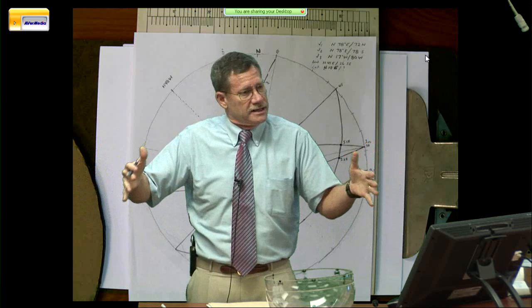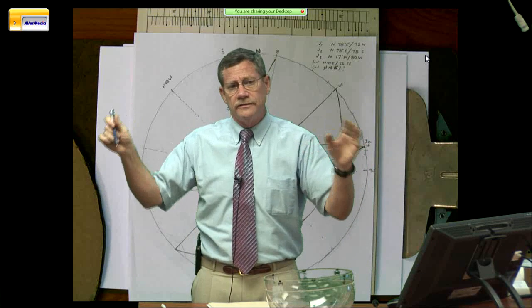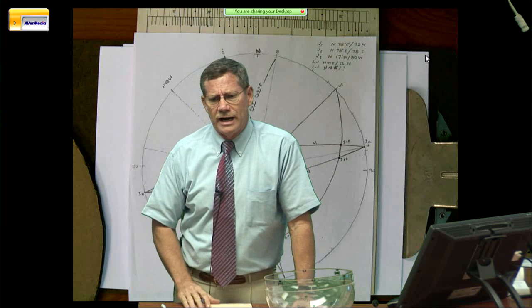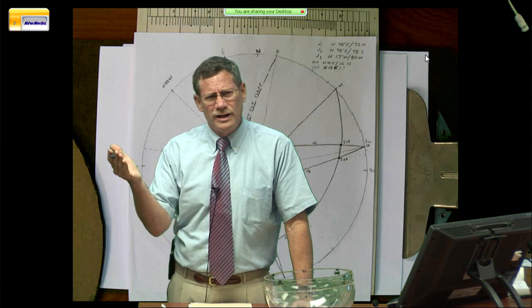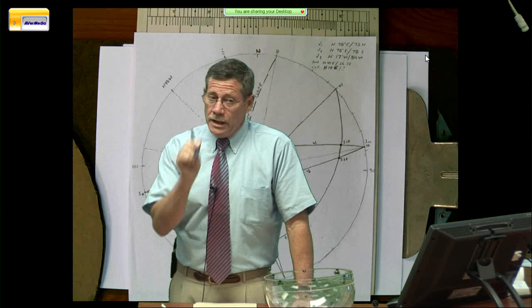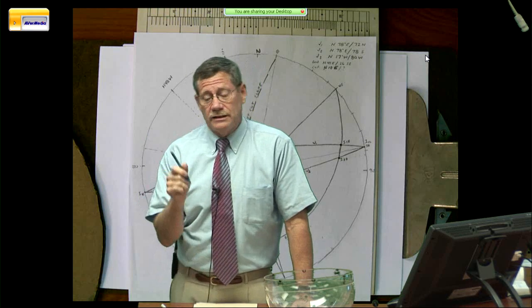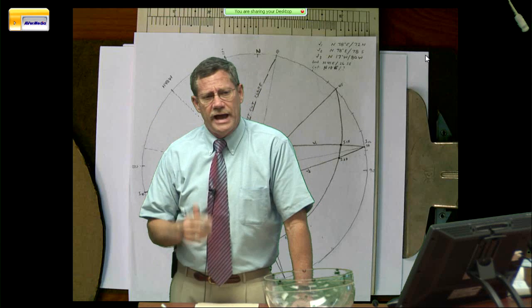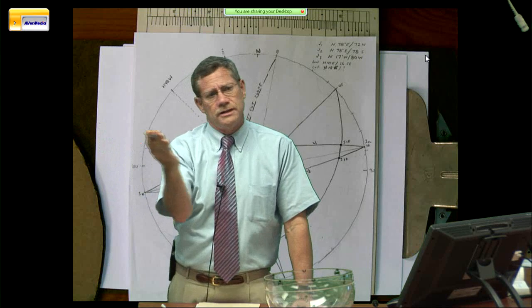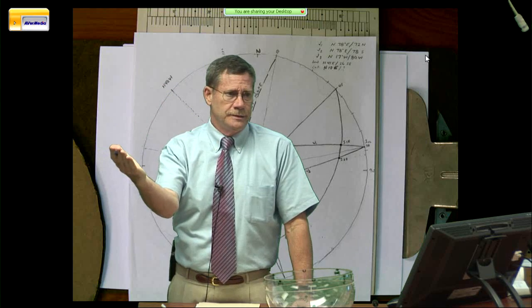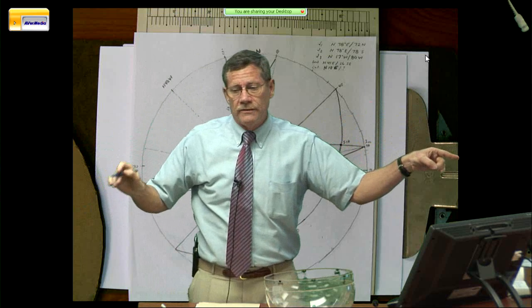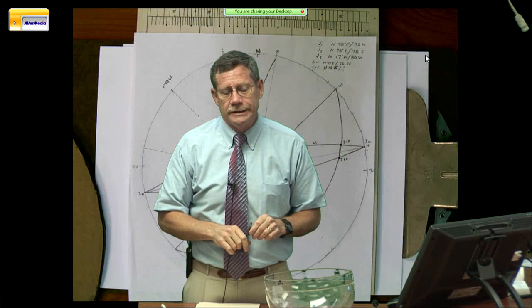So we want to get in that discussion session and have them just observe, or sometimes have them bring up, well, I ran into this problem today, and what should I do here? I got a few joints out there that really have unfavorable inclinations. Do I really need to incorporate that into the whole analysis? You don't always. Sometimes you get out there and you look at it by inspection. We call that the observational method. And we say, uh-oh, right here, we got a shear zone or we got a fault and it's an aberration. We're going to have to do something right here that we don't have to do over here and over there. That's good engineering judgment being exercised.